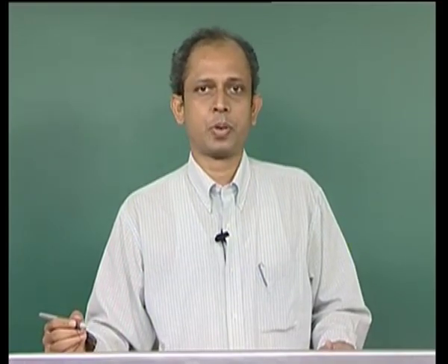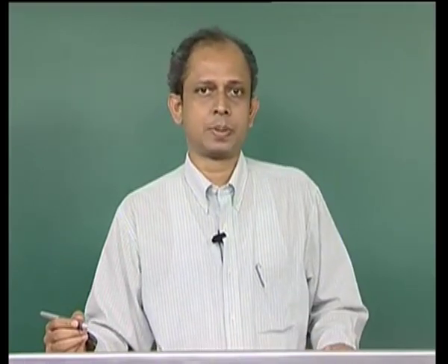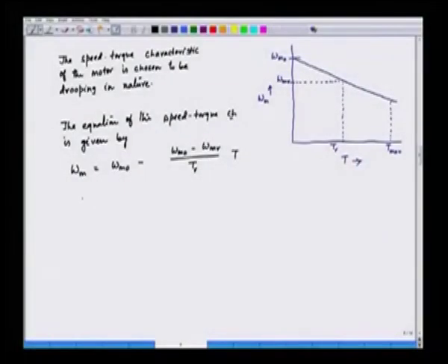So, we can very easily determine the nature of the torque speed characteristic. For a given torque, we can also find out the corresponding speed. So, this is the torque speed characteristic of the motor. Now, what we have, we can apply the dynamic condition here. We know that whenever a motor runs, it basically obeys a dynamic equation, and the equation is as follows. So, we know that J d omega m by dt is the inertial torque. We have here the moment of inertia is J, and d omega m by dt is the angular acceleration